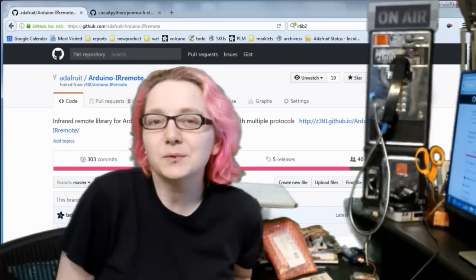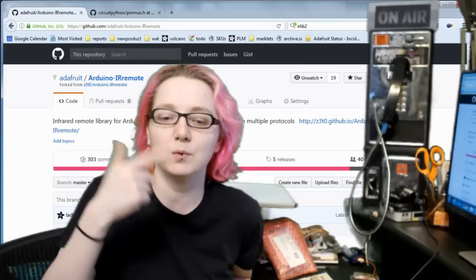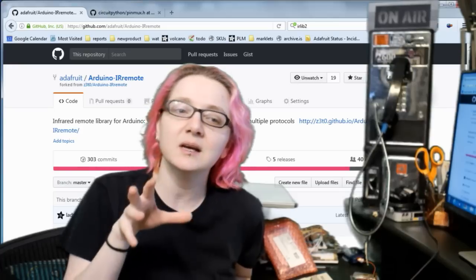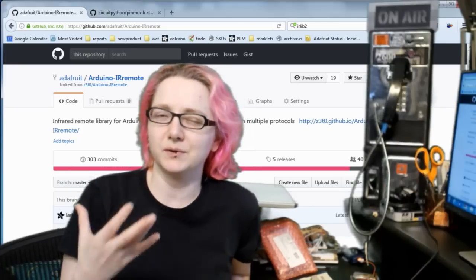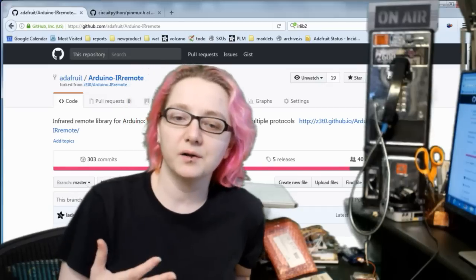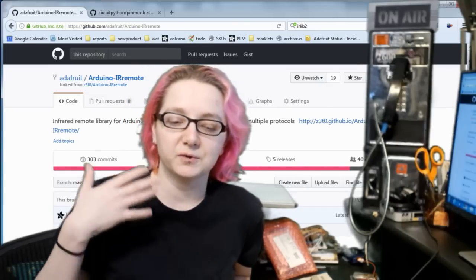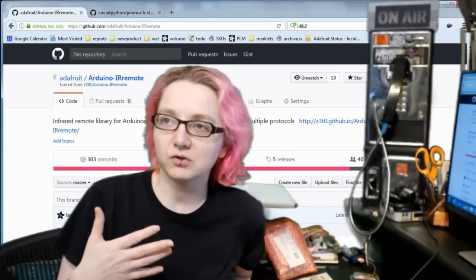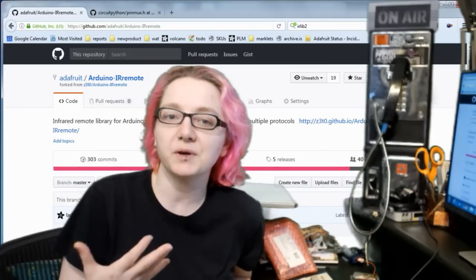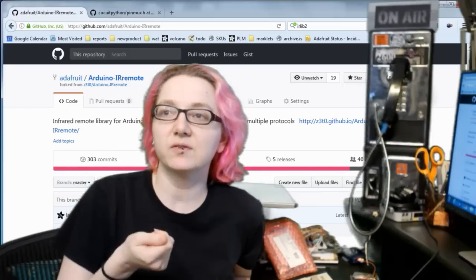other than that, it's kind of similar to wireless, except you don't have bidirectional communication. You have to have one transmit LED and one receive LED basically for each set, rather than trying to multiplex an antenna. But other than that, it's very similar to wireless. You'll have protocols and layers of filtration and error correction on top of it because, like all wireless protocols, IR is not perfect. Light can affect it if you're not line of sight.